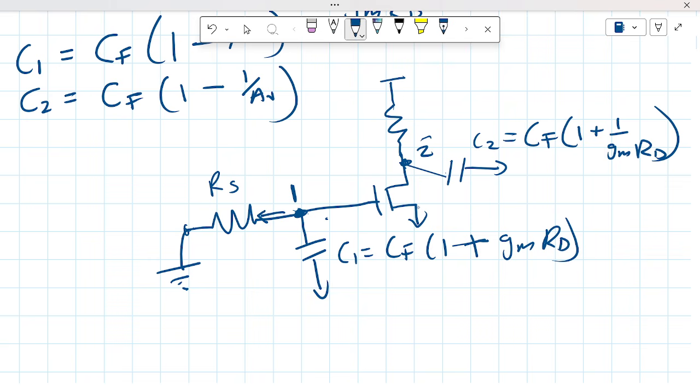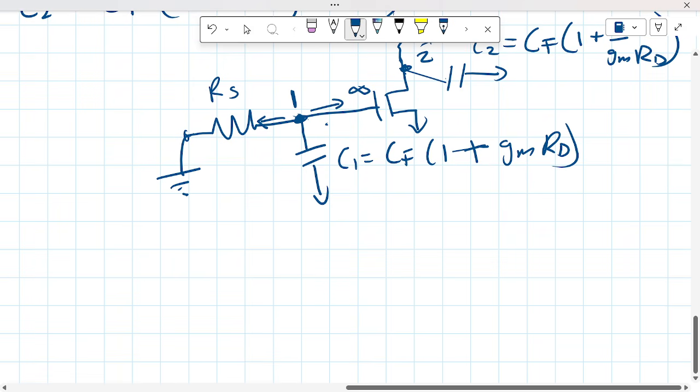We see some here, we see another resistance here, but the resistance here is infinity, assuming low frequency, which is a good approximation to make, even though we cannot always assume low frequency, since we are taking frequency into consideration in the frequency response. But let's just assume the frequency is not high enough to change the capacitance value here to get a proper impedance. So we still assume infinity here.